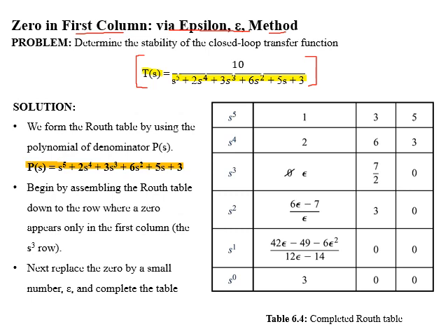So we will make a Routh table and label each row with Laplace variable s, starting from highest power, which is 5. First row will be labeled as s5, then s4, then s3, and up to s0. Now we will place the coefficients in first two rows of the Routh table. Upon calculating the elements for third row, we get a 0 in first column.